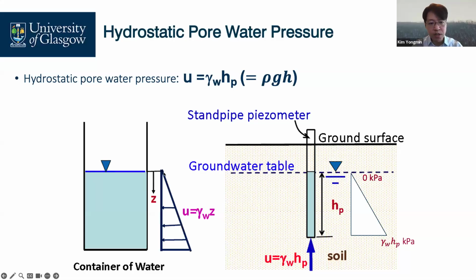This hydrostatic pressure gradually increases with depth. Yes, it is true. So when you install your standpipe piezometer, like a straw, a hollow pipe, into the ground, we can read the water height, which is represented by hp.